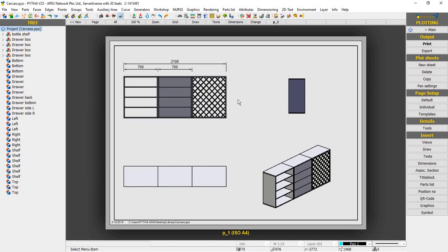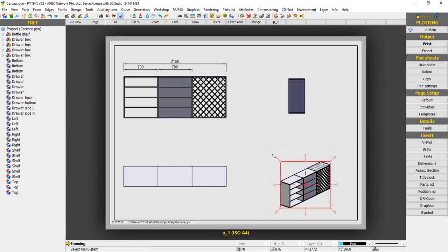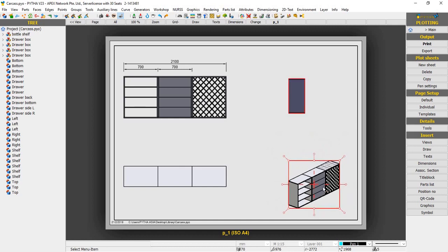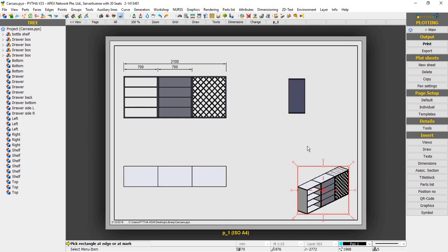You might be thinking, how can I move my detail around? How can I move my drawings around? Let me demonstrate with the bottom right hand corner over here. I can double click and this red box appears. I can scale it down manually by dragging over here. You can see where my mouse is. Look for the outermost one and bring it down. And I can move it using this crosshair here. This crosshair allows you to move it anywhere. Click on it once, and when you're happy with the position, click on it again to confirm. Then you right click to remove any further adjustment.